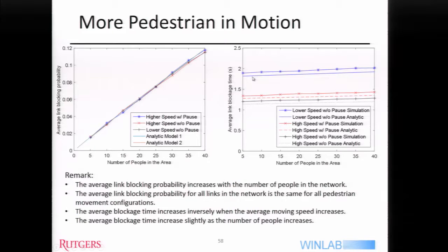So we've been doing measurements in collaboration with the university in Chile. If your link is short and people are milling around, then what really matters is a person in proximity to the antenna, because what matters is in proportion to the spot size. You draw it as a line, but it's really a beam. The beams are not all that narrow. Remember, we're talking about 16 beams, so beams of 10, 20 degree beam width.